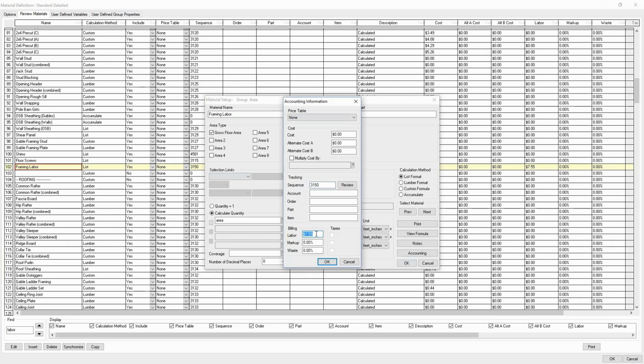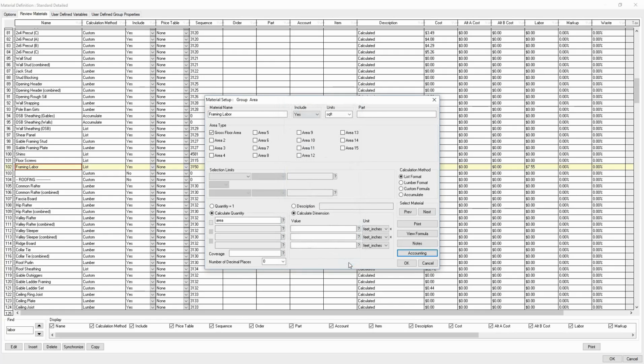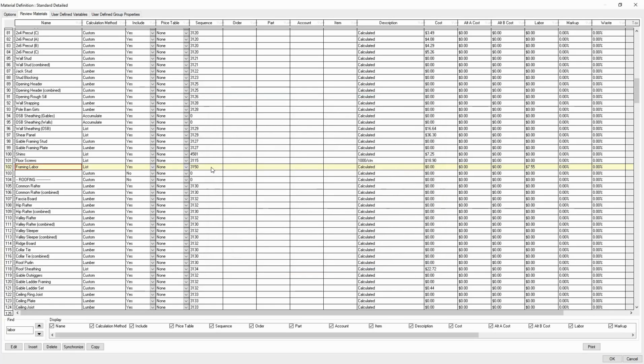Now what I'd like to do is, the garage was not calculated in there, and so I would like to come in and have a secondary formula that calculates this for that area, just so we get that area calculation out. We'll have that list to the report as being unheated, as kind of the unheated area, and for today's purposes, we're just going to use the exact same sequence number of 3150 so that it lists in the same spot.